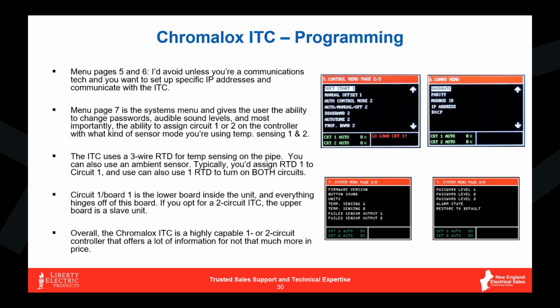But menu 7 is a good one to be familiar with also, because this allows you to adjust your temperature sensing. So again, if you want to tie both circuits to a single temperature sensor, you do that in this menu 7. You can also change your passwords in here, restore the model if you need to, things like that.